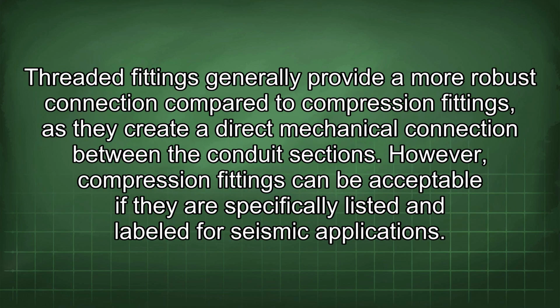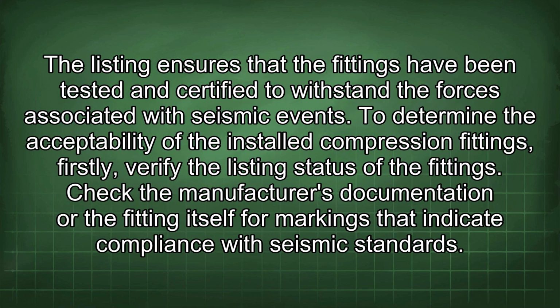Threaded fittings generally provide a more robust connection compared to compression fittings, as they create a direct mechanical connection between the conduit sections. However, compression fittings can be acceptable if they are specifically listed and labeled for seismic applications. The listing ensures that the fittings have been tested and certified to withstand the forces associated with seismic events.